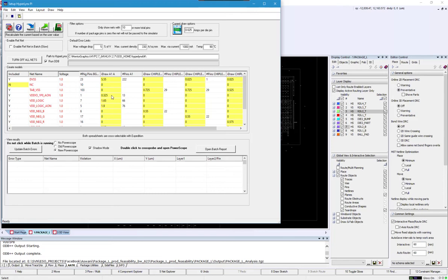Now, why I call it big rock is we're not setting each pin on each die with the amount of current that each one draws. We're just making a general assumption that all pins are running at 25 milliamps. You can absolutely go in and tell each pin what current you want, but that's not big rock analysis. That's not the quick setup. That's actually going into the tool, driving the tool and setting up the models. Part of the big rock setup is that it makes all the models for you based off of this number.